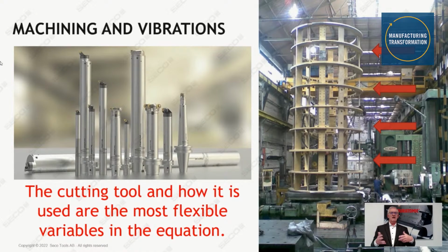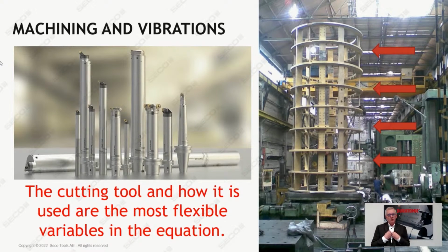One could say, okay, I modify the cutting tool. The other way of working, personally I prefer that one before changing the tool, is evaluating cutting conditions and seeing if, with an existing tool but with another machining strategy, with a modified combination of cutting conditions, I can make the vibration disappear.